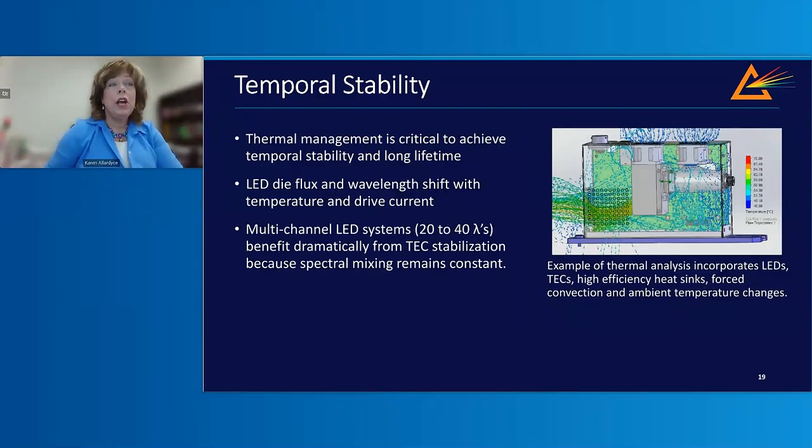So you have to be very careful what LEDs you choose around those regions, and also to control them very specifically to minimize temporal instability. At IOI, we control to 0.1 degrees C to ensure that the spectral output remains constant and captures behavior around those band edges.